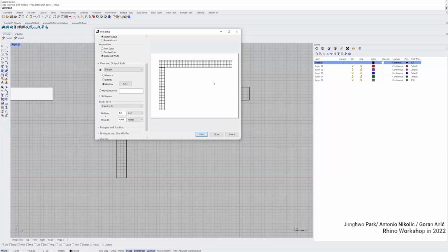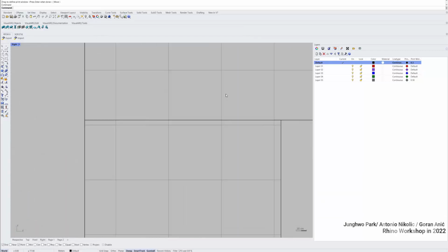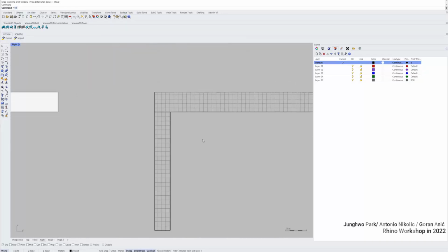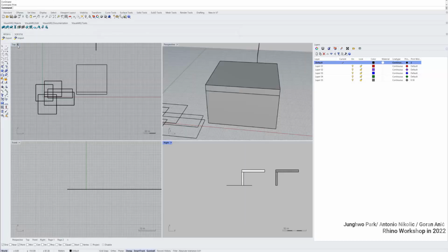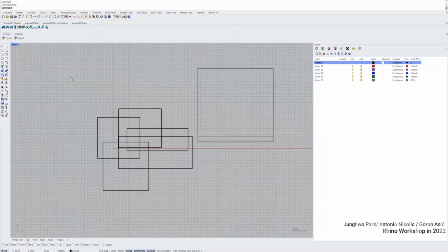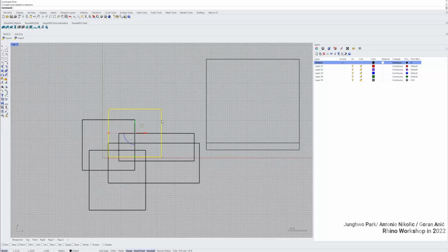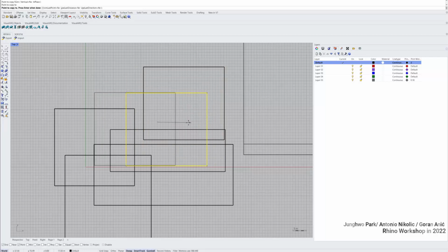You will see the different line weight actually, but it doesn't really show in this small screen. But you get what I mean, yeah? It kind of shows here if I turn it off. Let's make the thickness a bit bigger too. It doesn't really show in here, but you can see the difference. So that's just a short demonstration of how you can use these different curve tools, and that you can document just like AutoCAD: trim, extend, chamfer, fillet, copy. You can type copy, move, exactly the same as AutoCAD, everything the same.